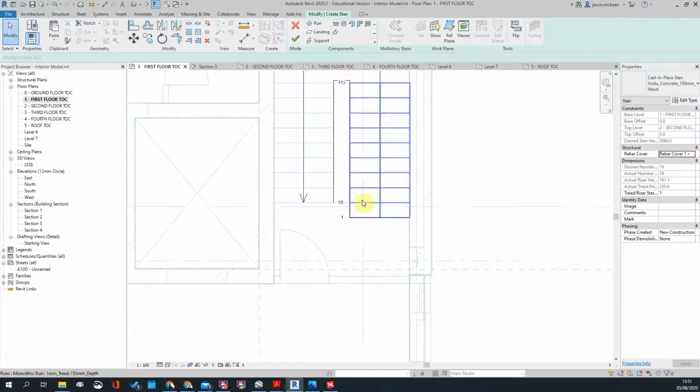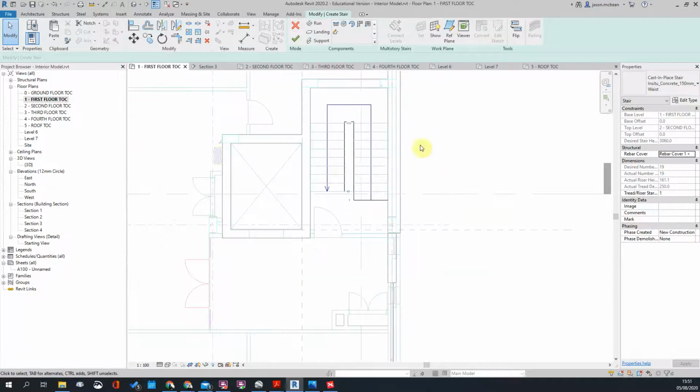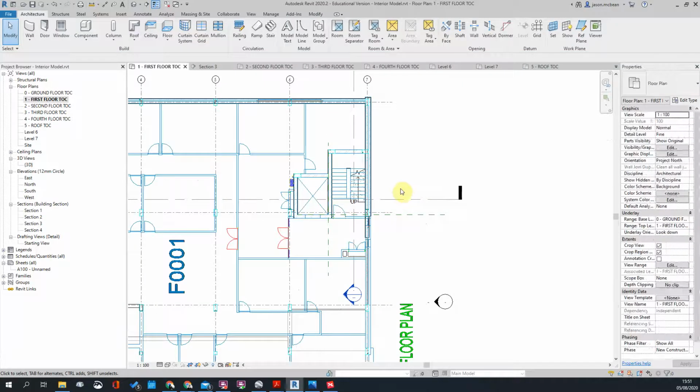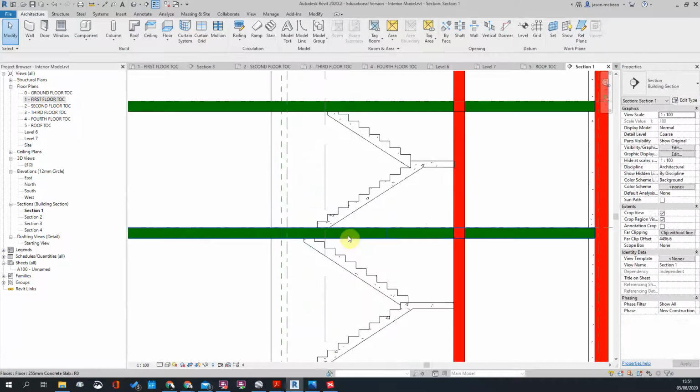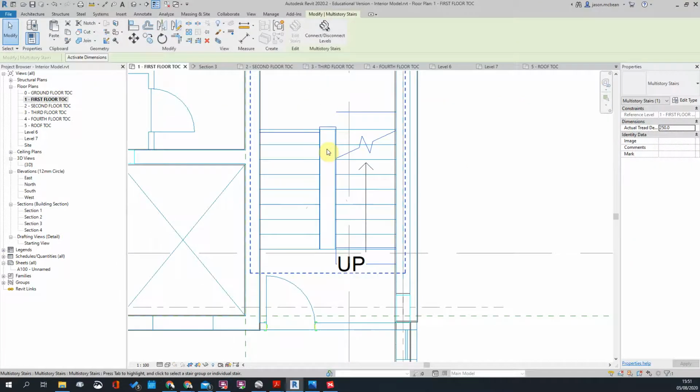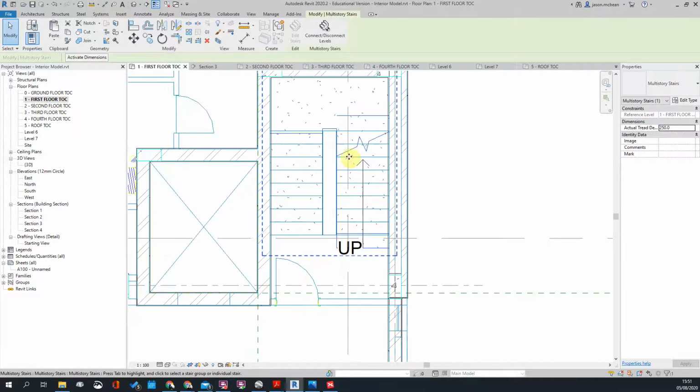But generally we do not do this, because you see here it's created an unequal landing, you might find there'd be an extra step when you go up. You know, generally we try and make these equal. So I think whoever drew this hasn't drawn the steps correctly either. Okay, so the only way you can get around that is by adjusting the landing. So let's do that quickly. So let's go to edit steps.